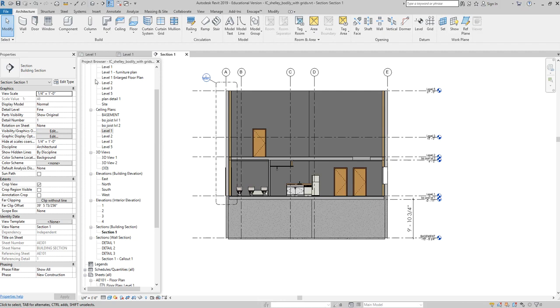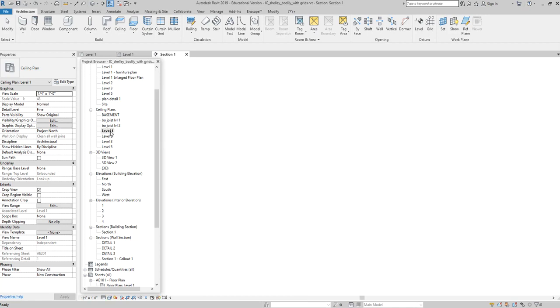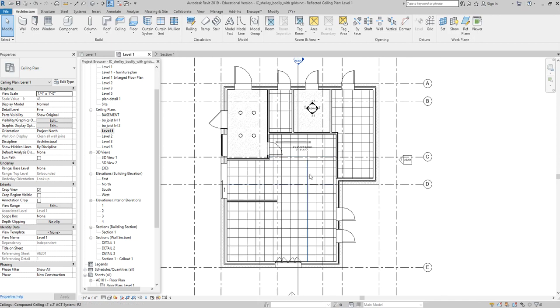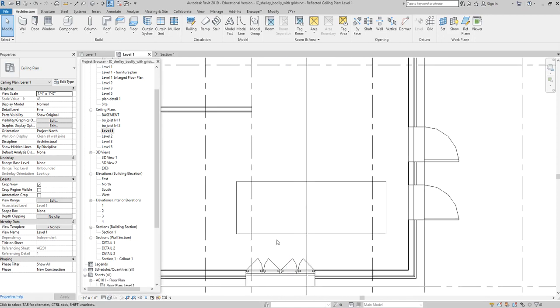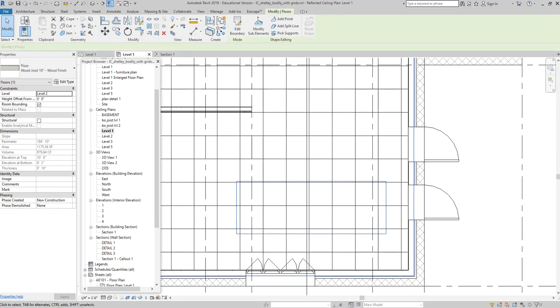Sorry guys, I just remembered one thing as I actually navigated right there. One thing I quickly want to tell you, and I'll be done, I promise. You can leave openings in your ceilings, okay? So I'm going to change to a wireframe view because I want to be able to see the floor above my ceiling. So I'm going to go to wireframe. And do you remember how the wireframe allows me to see the opening in my floor above, right? So my floor above has an opening for stairs, okay?